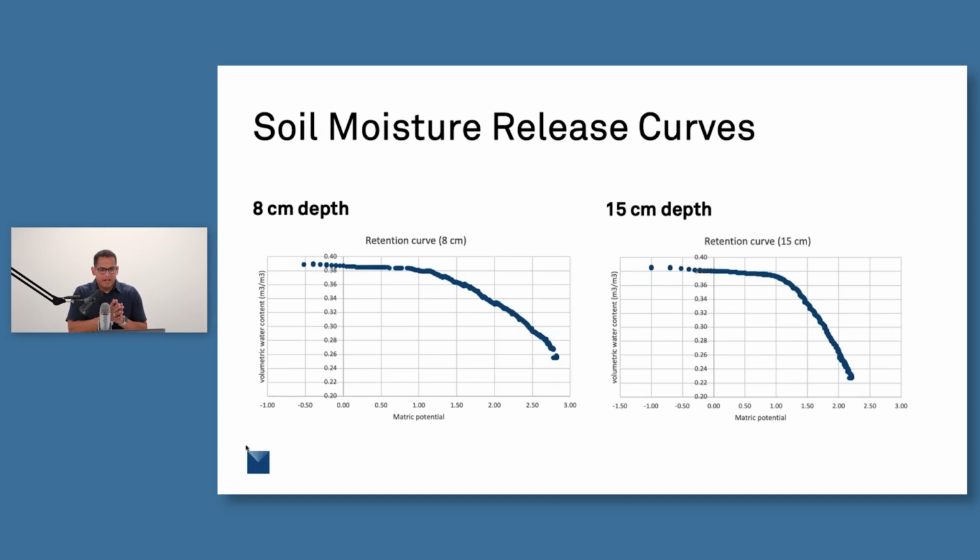So here, if we actually pull the data for both those sites and plot the water content versus water potential, we see what looks exactly like a typical soil moisture release curve for these sites. And another thing that I think is really cool is, one, we had a really good section of data here, and we were actually able to plot this and generate some van Genuchten functions off of this and get our field capacity and our permanent wilting point.